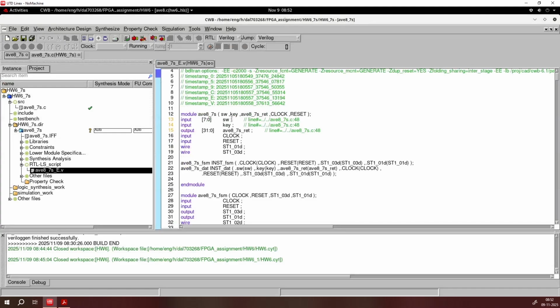Here for our RTL code, we can see the switch, key, and the signal, our 7-segment signal. Also, we can see clock and reset being implemented automatically. Reset here, what it has automatically generated is basically a circuit reset. Once that signal is sent, it wipes out all the memory of the previous input and makes the average 0. So once this Verilog code has been generated, we can take this Verilog code into Quartus Prime and perform further steps that are required for FPGA, that is pin allocations.